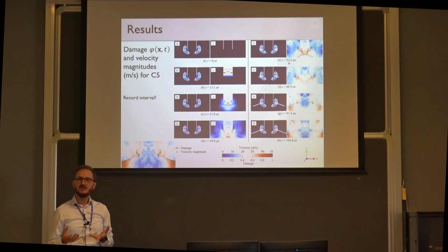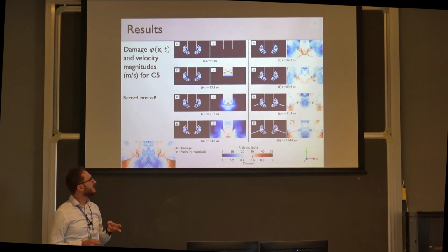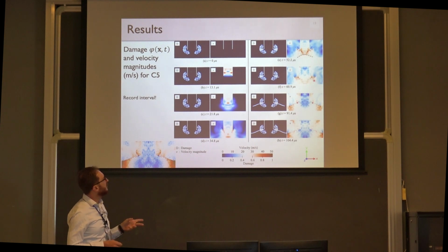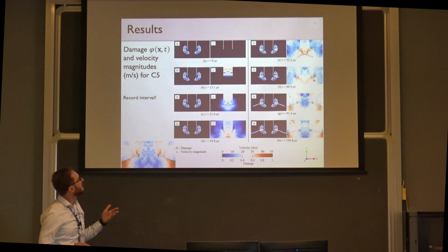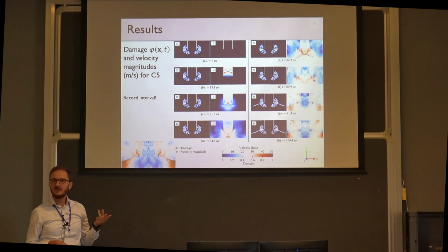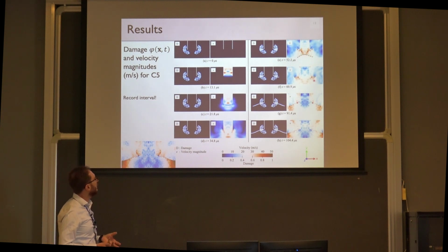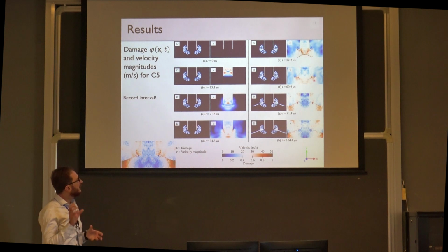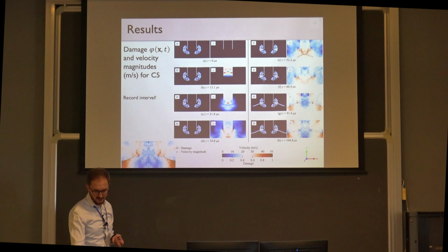The transition between mode 1 fracture and mode 2 fracture starts with the mixing of the reflection waves and the compressional waves. But the recording time is a little bit of a problem. Here I recorded the data about every 4 microseconds. Maybe we need to record at smaller time intervals to see the wave propagation better.